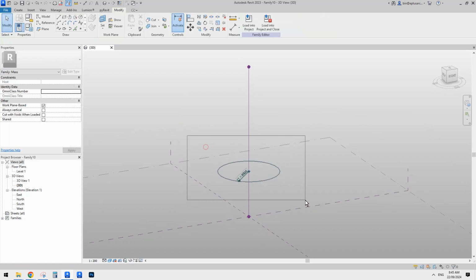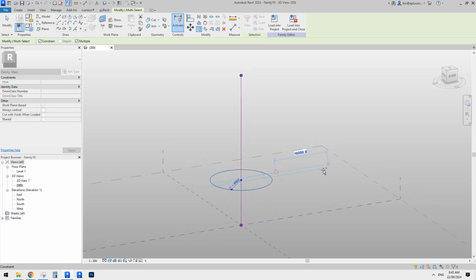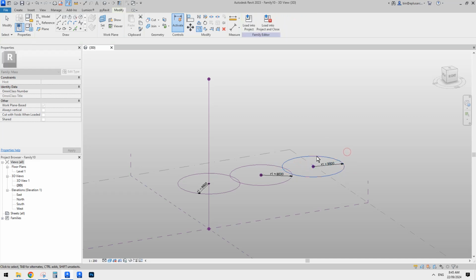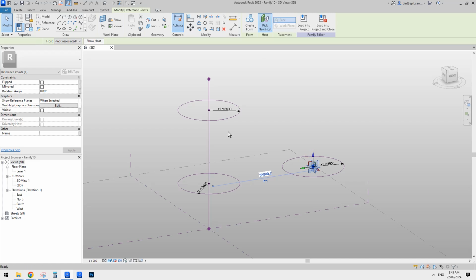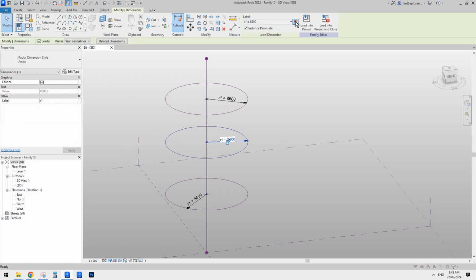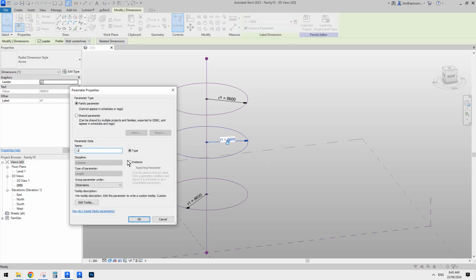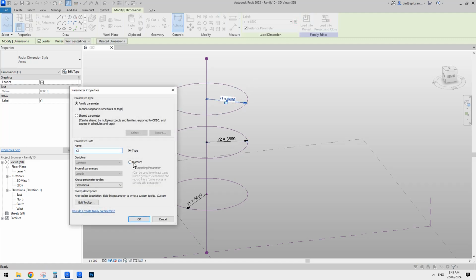And then we're going to copy them. So select everything, point, dimension, and the profile, copy, and paste, 1, 2. So we need three in total. Select the point, pick new host, select point, pick new host, and of course we're going to change the parameter. So for this one, we select this and create a new one. I'll just call it R2 instance. Select this one, create R3 instance, and okay.